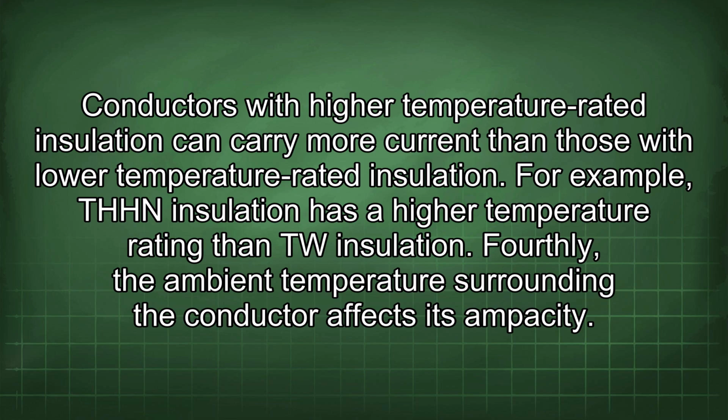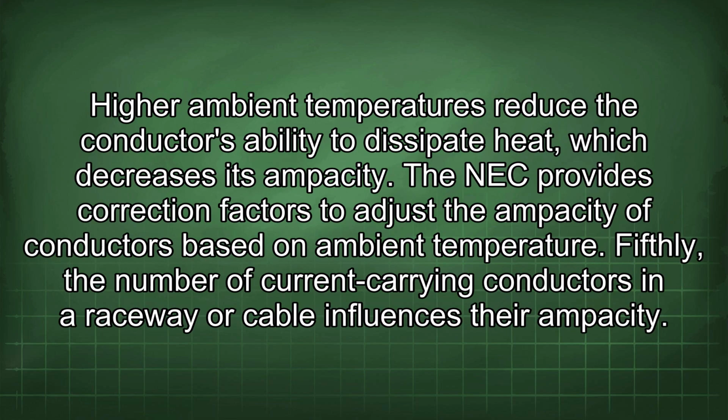Fourthly, the ambient temperature surrounding the conductor affects its ampacity. High ambient temperatures reduce the conductor's ability to dissipate heat, which decreases its ampacity. The NEC provides correction factors to adjust the ampacity of conductors based on ambient temperature.